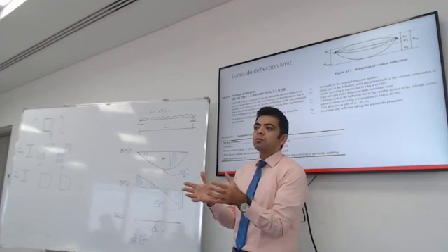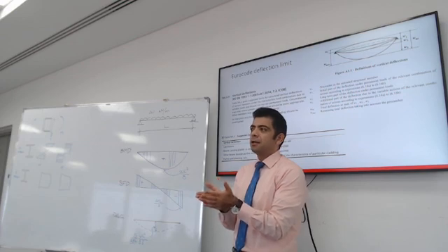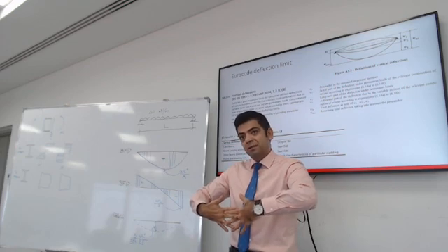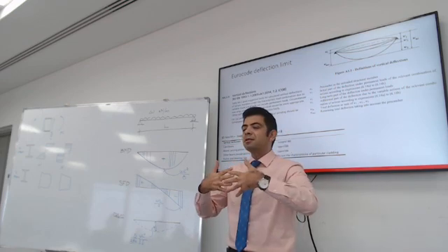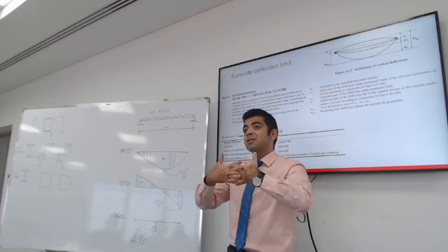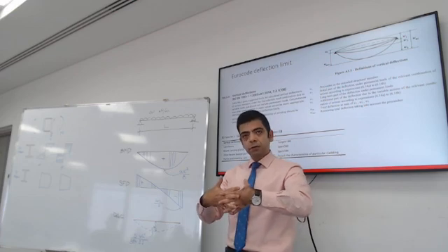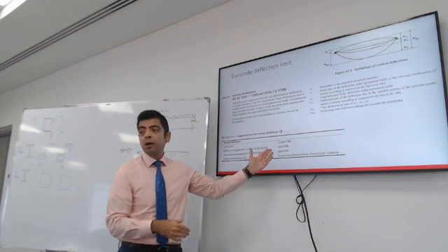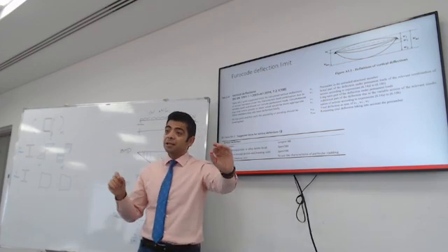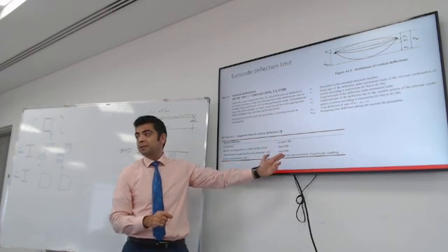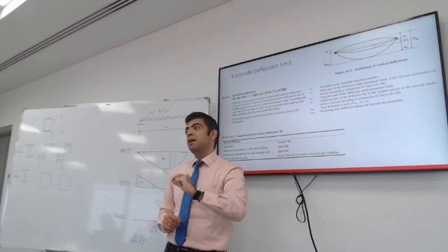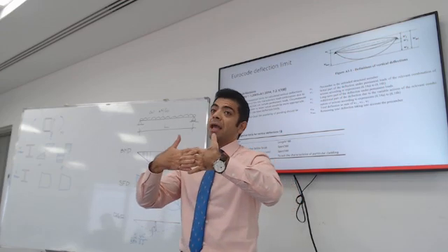So you still need to do something about it. It needs to be a reasonable design. You don't expect your beam under its own weight to be sagging all the way like this. So it's good standard practice to either provide a camber or make sure that the deflection under the self weight is not excessive. Once you do that, you follow the limitation of the code. The code ties the allowable deflection to the span. It's always a ratio of the span, and it tells us the allowable limit for different elements, depending on what's attached to the element.